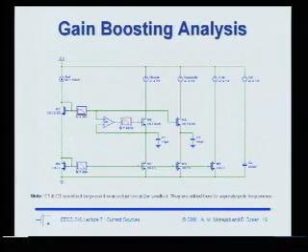With a regular cascode, this voltage here is being held constant because the VGS of this device is relatively insensitive to variations of current, and this gate voltage is constant. So here we're doing one better. We're introducing even more gain into this loop to hold this voltage constant. Okay? Questions? Comments?